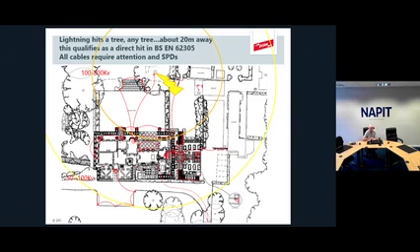Now, I don't think that those cables actually go to a distribution board, which is where the SPD is going to be located. It might go to a control device, such as a timer or a photo cell or a contactor, maybe a dimmer rack, something like that. Now, I have to think about where these external locations are going to, and would that location within the installation like a surge going down it? So it might be that the SPDs that you've already seen in the distribution boards may not be enough. There may be other locations where you need to think about where those cables go from the outside in.